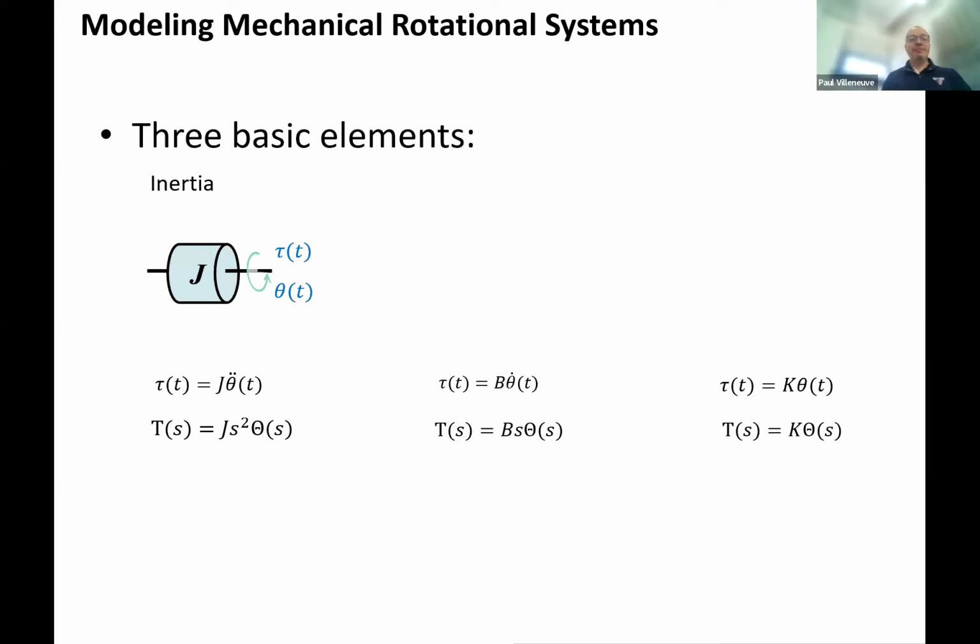So we use torque, and our torque equation is going to be equal to J, which is our moment of inertia term, multiplied by acceleration. We're going to do things in class, just to simplify things, as a function of position. We're no longer looking at the distance from something, because it wouldn't make sense to have a nominal position to say that this is the zero position and then keep track of the distance. It would always just keep increasing and increasing. It wouldn't be any value.